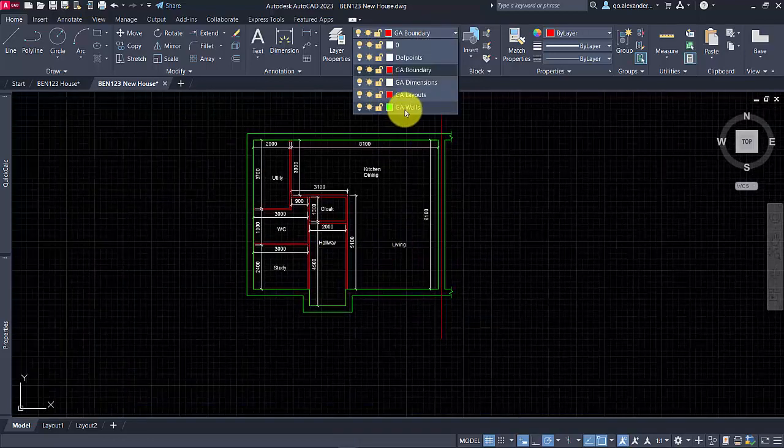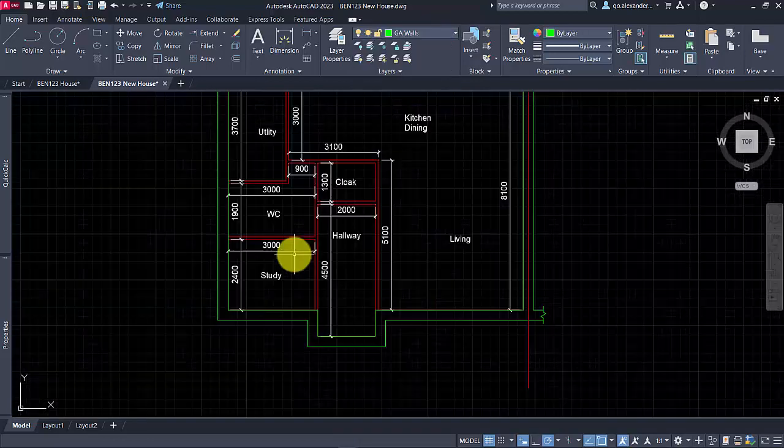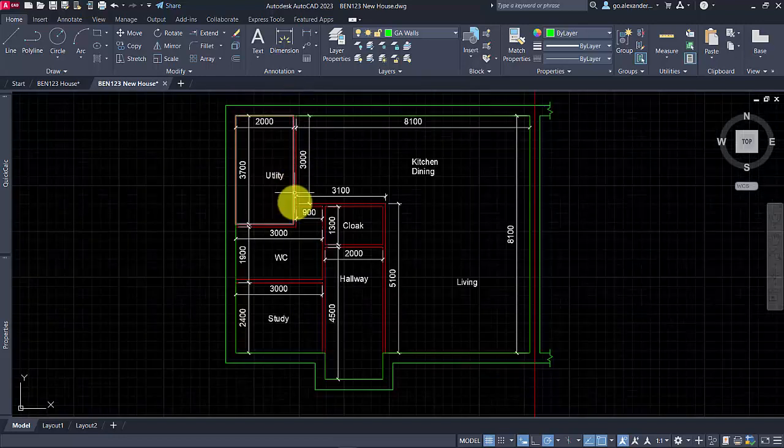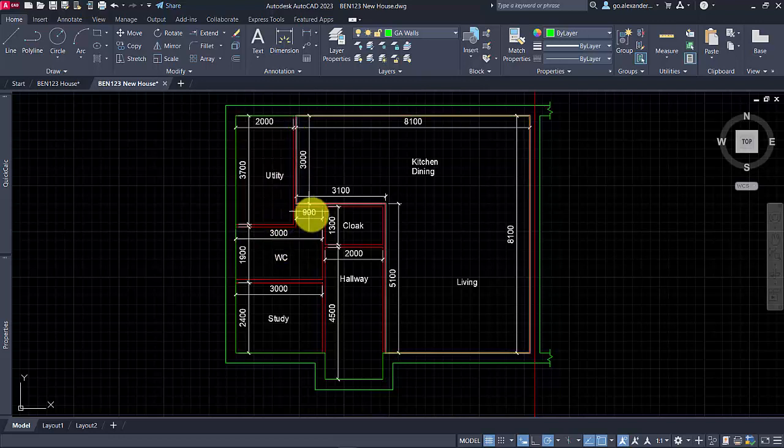At this stage we need to go back to the walls layer, and one way that you could do the internal walls is to trace over the rectangles. However, sometimes that can create issues if you have been inaccurate in any of your stretches or resizing of the rectangles.